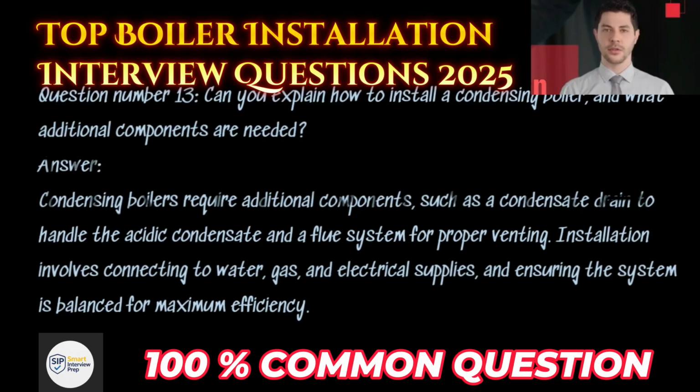Question number 13. Can you explain how to install a condensing boiler, and what additional components are needed? Answer. Condensing boilers require additional components, such as a condensate drain to handle the acidic condensate and a flue system for proper venting.